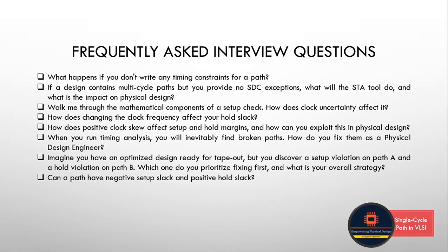So in physical design, engineers exploit this through useful skew. Here our EDA tools will intentionally delay the capture clock of critical paths to fix setup violations. So intentionally we are using this useful skew. This technique basically borrows the timing slack from non-critical paths with margin to spare, allowing the entire chip to run at a higher frequency without changing the logic gates. That's it.